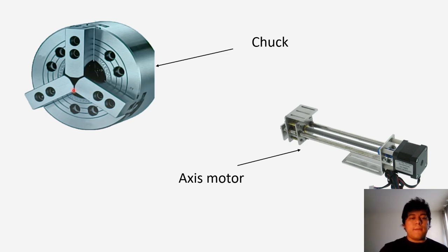So in this case, with 3 it's more than enough, of course, in some procedures, but you will have to pay attention. What material are you having? What geometry do you want to achieve at the end? And just like slight notes, I'm just gonna make a quick note in here. Many people believe that the same chuck works for all the materials, but some unfortunately apply more pressure on the end of the material that ends up hammering your material. What does hammer mean? It means that it damages your material.